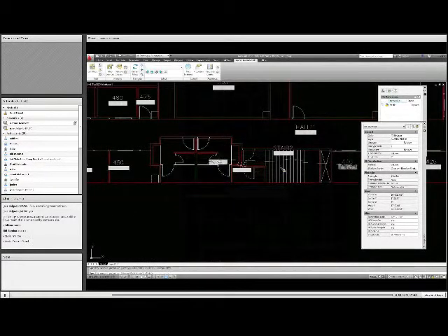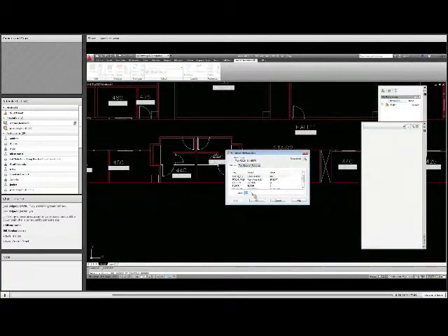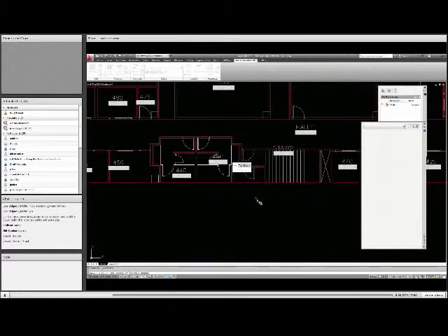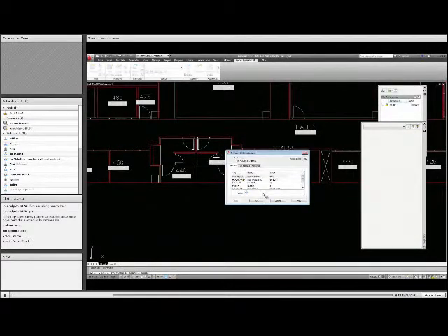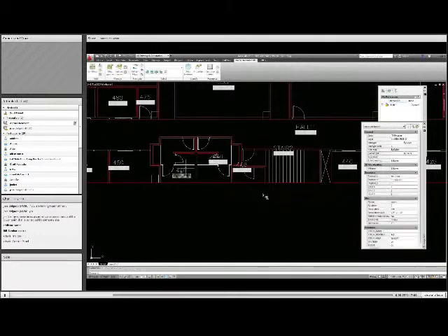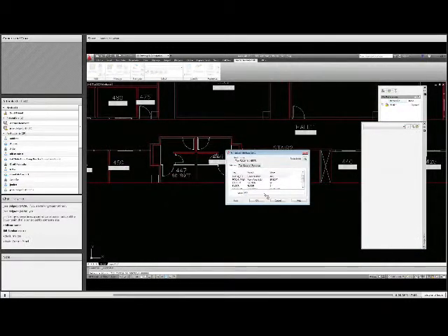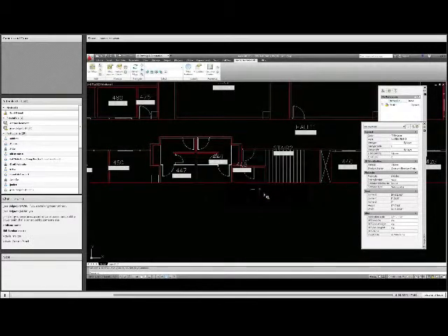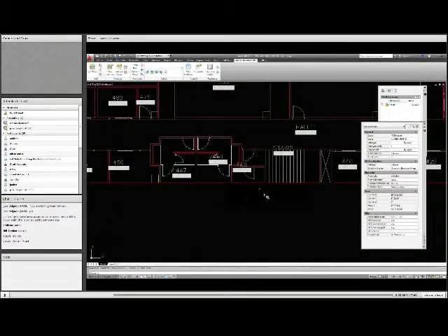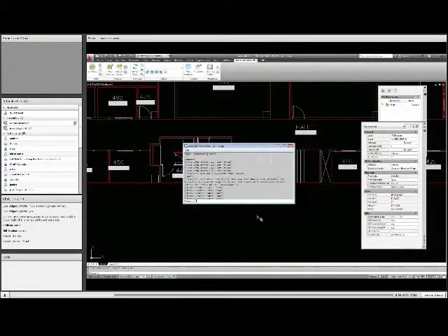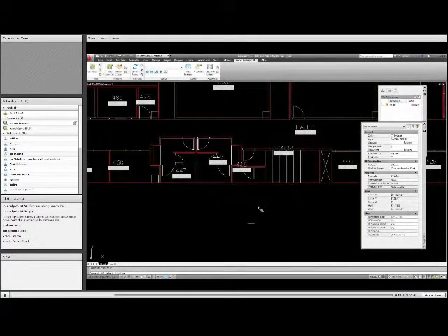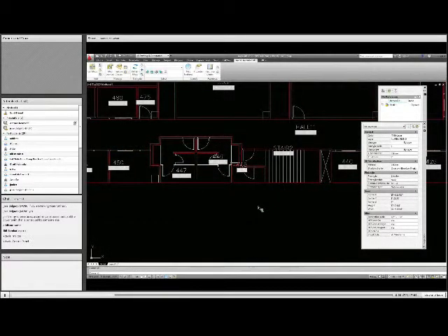So that about covers the floor plans. It's pretty straightforward. It's built on having a field in our room number block that links to the polyline for that room, and through custom utilities, creating feature classes and transferring the data from the block to its associated polyline, so that we have all the data with the objects we need in GIS, so that when it comes time to do the translation, it's a very straightforward process. There's no complex spatial intersection with the room numbers, where room numbers don't fit inside the rooms. That sort of methodology has caused a lot of problems.